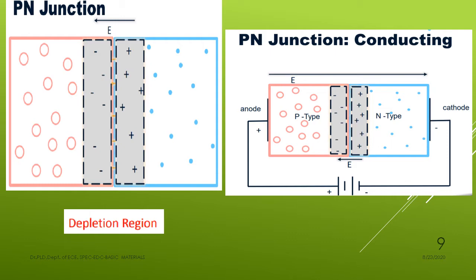That particular current we call the diffusion current. Because of applying the external voltage to this combination of P and N semiconductors, a larger number of charge carriers, the majority charge carriers, diffuse from one region to the other, which leads to the diffusion current. This is the basic phenomenon of how current flows through the diode, based on the movement of charge carriers.